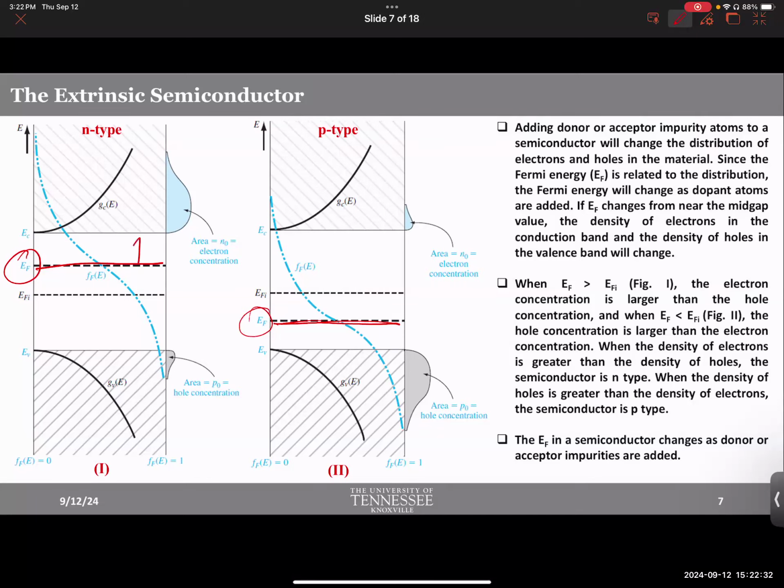And if there is one takeaway that you should consider from this concept, if you could modify this Fermi level, take it up, this will grow. Or if you could reduce the Fermi level somehow, take it closer to the mid gap, this will reduce. So you could change the number of carriers available in the conduction band by dynamically modulating the Fermi level, which is very powerful, by the way.